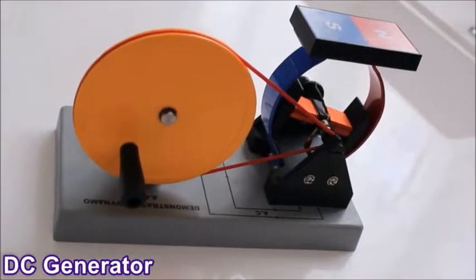It uses many methods in working. One of the common methods is the potentiometric method, in which 4 electrodes are placed concentrically in a circle, applying an AC circuit on the 2 outer pair, and then measuring the potential difference from the 2 inner pair. It uses Ohm's law and the surface area of the electrodes along with the distances to measure the conductivity. The electrodes in this case are made from platinum. The other method is to make the electrodes filled with an electrolyte of known conductivity.